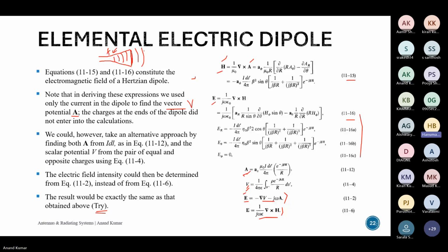Actually, sir, there are two compromising values here. One is the return loss performance, where the tuning is happening from 0.2 to 2 gigahertz. That is fine. But when it comes to the radiation pattern, then I'm not satisfied with that. So sometimes in some Vivaldi designs, I'm happy with the radiation pattern, but not with the return loss performance. So I have to compromise both of them together. So that's where I'm looking into.